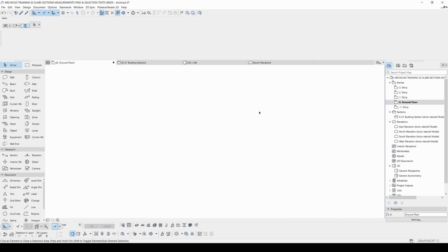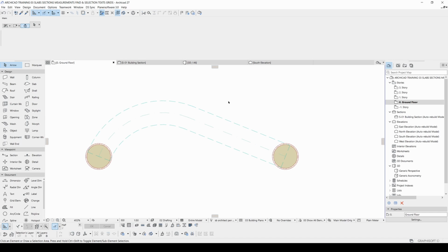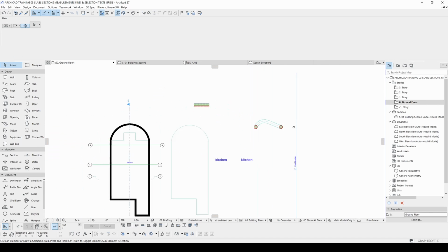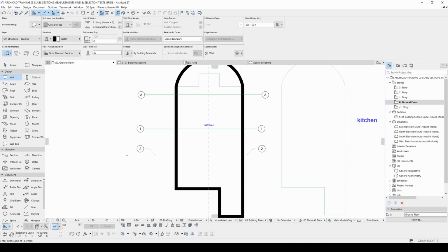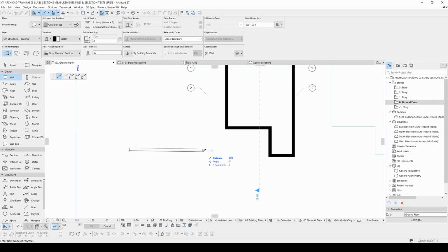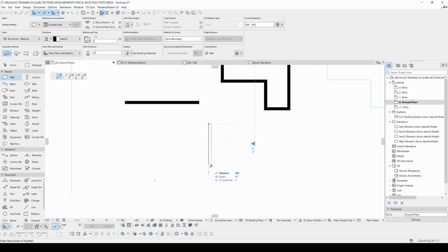Of course, you can switch back to the circular or rectangular and change its building material and element. Let's switch back to the floor plan, and I will show you how to edit your walls. For instance, I'm going to hit Alt and click this wall, and I'm going to copy that wall. And I'm going to create another.